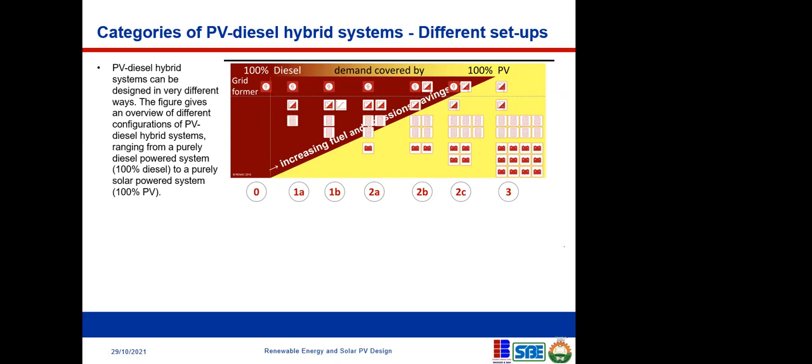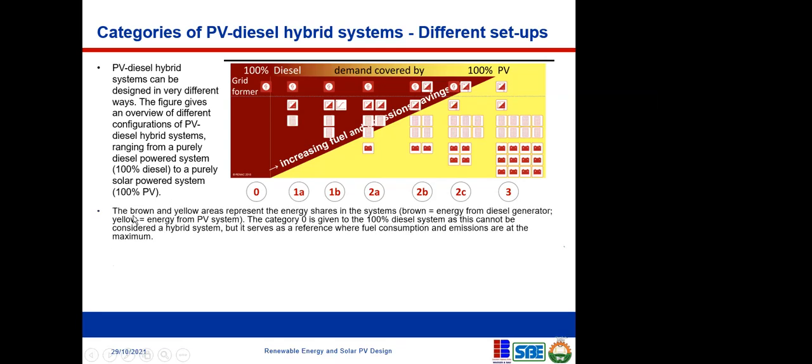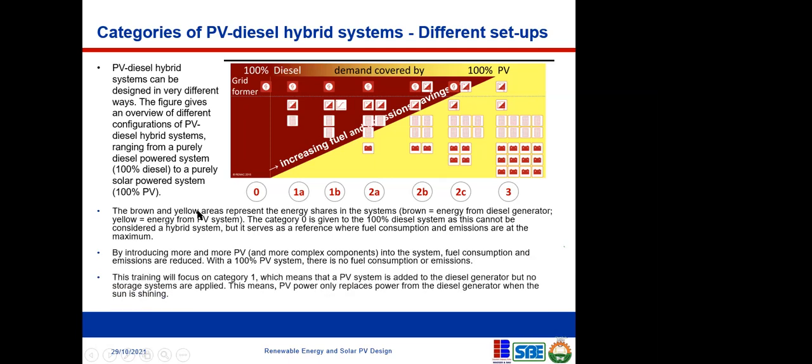But in most cases, people don't give so much attention to the health of these batteries. You don't pay attention to the depth of discharge and the temperature, and there are a lot of things that affect the life cycle of these batteries. Okay, and they don't come cheap; they are very expensive. So if you want to do away with the generator, your battery pack has to be large, to take care of any load that you have to put in at night, up until the sun comes up again to charge your system. Okay. So this literature just explains what I've just said now. So let me just move ahead.